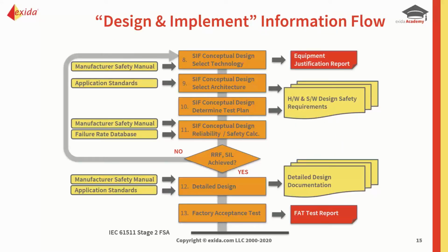And as we see here, when we go through the design phase in a little more detail, the focus is on selection of the technology, and we have to do an equipment justification. So again, it's hardware oriented. The architecture is looking at how we're going to meet our hardware fault tolerance if required for the SIL. And then how do we test it?